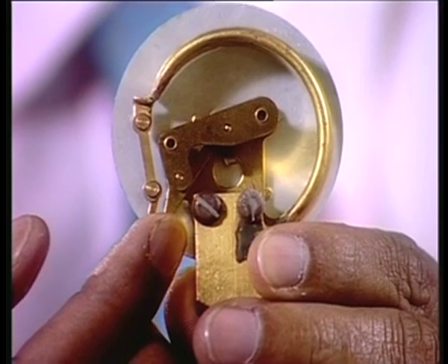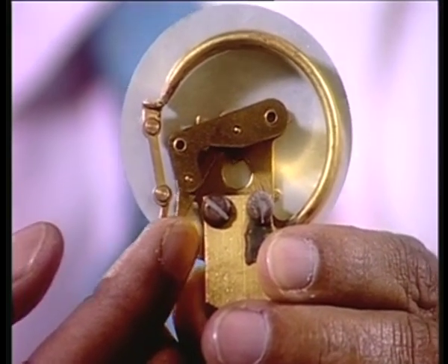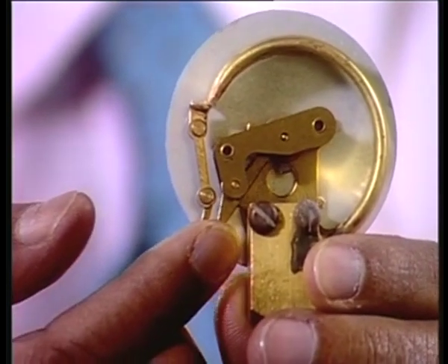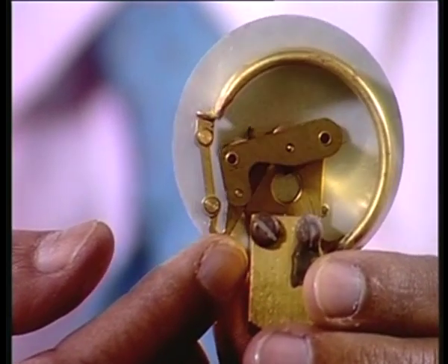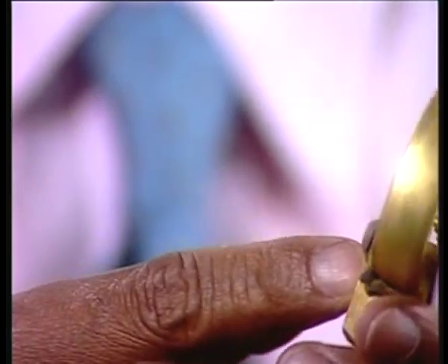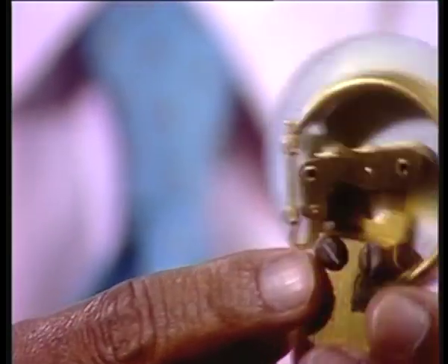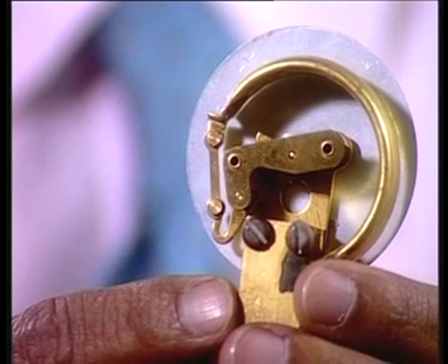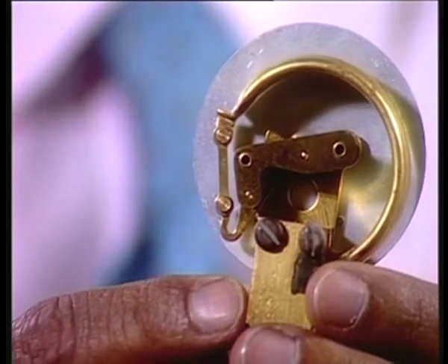The C tube is coming down, and we are getting the movement. So you have a hairspring also here, which will bring back the needle, and there is a gear also inside. You cannot see it from the front, but from the back side you can. The needle is fixed on the gear itself, right? So I get the output. So this is about the C-type Bourdon tube.